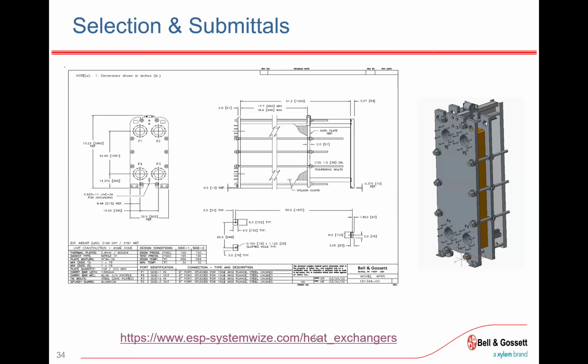On this, once you get to this point, usually what it does is it sorts it in terms of price. Everything's going to meet your minimum requirements in terms of pressure drop and so on, or your maximums in that case. It provides your lead time, connection sizes. But let's say you select your first one, you could say, okay, well, in this case, dimension B is 72 inches. So it's 72 inches tall. The frame is 23 inches. That's this here. And D is about 20 inches wide. So that works out well.